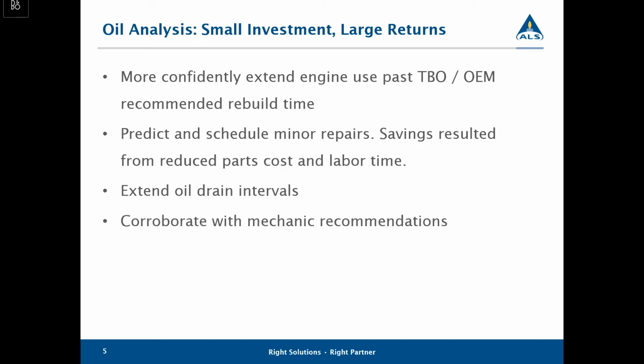It helps corroborate mechanic recommendations. This can be really important. It keeps everybody honest, which is nice. Instead of being told one thing and hoping that that's the problem, you can corroborate what issues might be occurring from the oil analysis. So if the recommendation is that it's maybe an accessory drive that could be failing, you can corroborate that with an oil analysis report and show that, yes, the elements on that report line up with these recommendations of what might be going on.